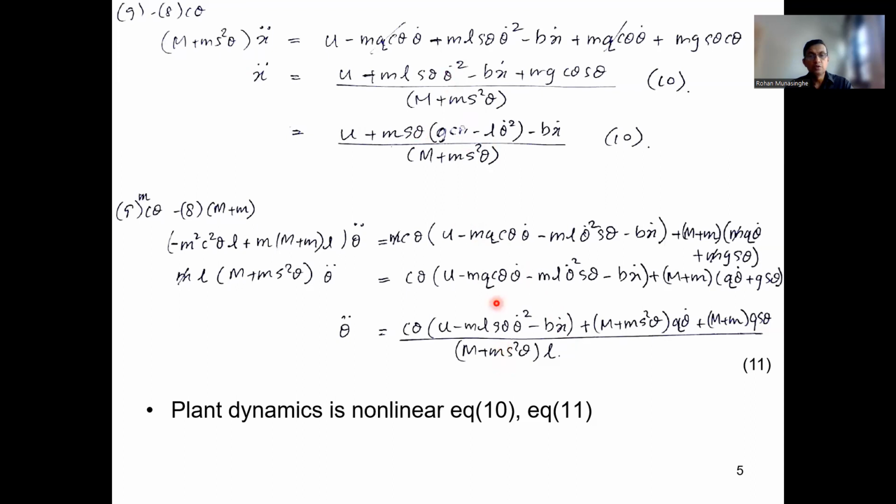Then we figured out these two equations are highly nonlinear. You can see sines and cosines, which are nonlinear functions, and you can see theta dot squared, right? So it's a seriously nonlinear model. Now, have we done any nonlinear controls? No, we haven't. But one thing we did was gain scheduling controls, where a nonlinear plant is linearized at different states, and then you develop a controller. So that's one approach to deal with nonlinear plants.